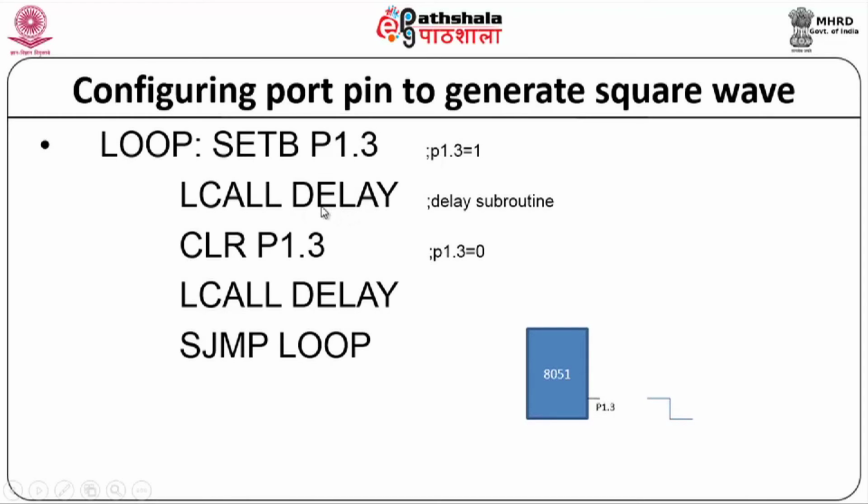This delay is a routine. LCALL is telling you that it is a subroutine long call, that means this delay subroutine is written somewhere far away. So, I will call it with a long call and go to that particular subroutine, run it, and come back. There I will not process anything, but instead make some delay statements, putting in a loop. So, I am not doing any work.